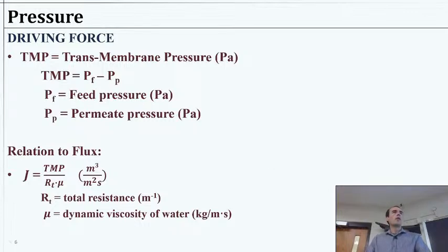another topic I hinted at earlier is what kind of pressure is required to actually push the water through the membranes. And so when we take a look at a given membrane, we're saying we have to achieve some specific flux that we might want or you would expect to have for a given membrane. And we'll call this pressure that we're going to apply transmembrane pressure. So pressure that's like we have some high pressure above the membrane, a lower pressure below the membrane or across the membrane. That differential is going to be that kind of a pressure gradient driving water across.